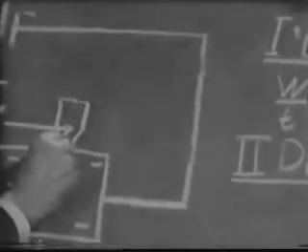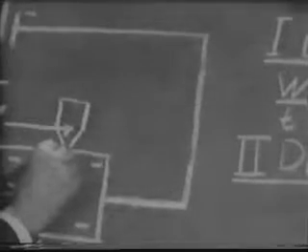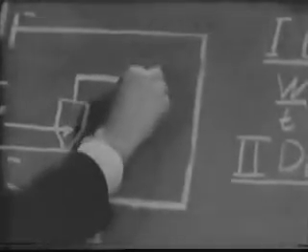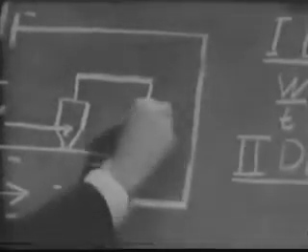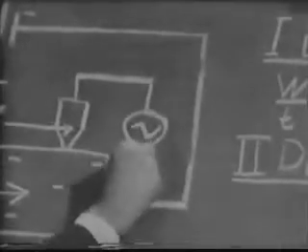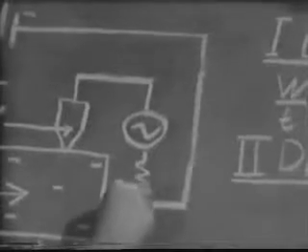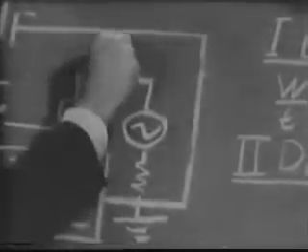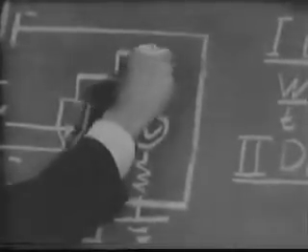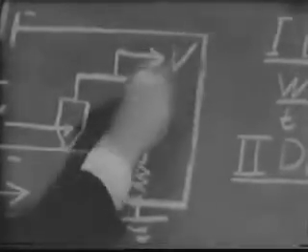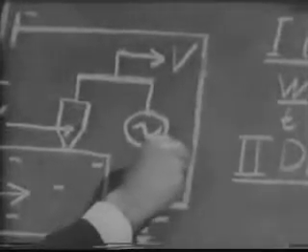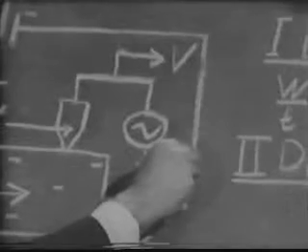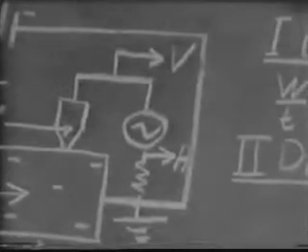This point contact to the germanium rod has a rectifying voltage current characteristic. This characteristic can be studied by setting up a 60-cycle alternating current circuit through the point. The point is connected to the vertical input of the oscilloscope so as to show positive voltage upwards. The resistor is connected to the horizontal scope input to show current from the point into the germanium as a deflection to the right.